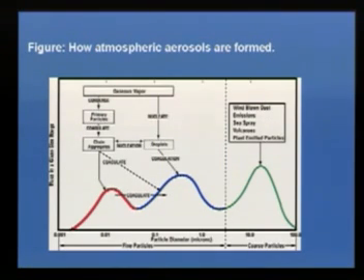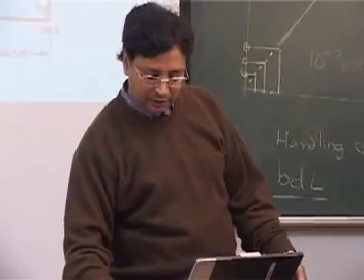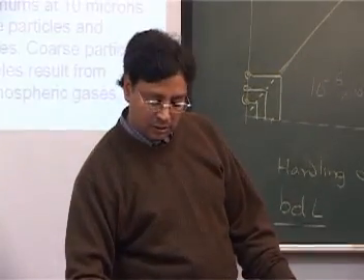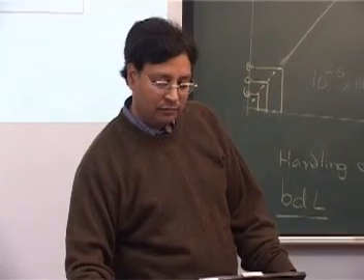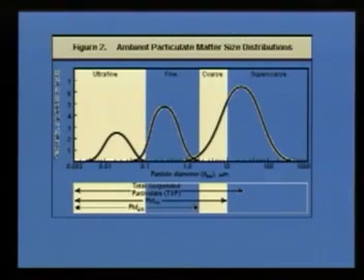That is how the trimodal distribution eventually becomes a bimodal distribution, and that is how the issue of PM 2.5 comes in. It's because of the two modes, and that's why sometimes we use the cascade impactor to differentiate between 0.25 and 10. Something similar kind of graph as you go away from the source. You remember we gave this range a name, coarse, between PM 2.5 and PM 10. Ultrafine and this and that.